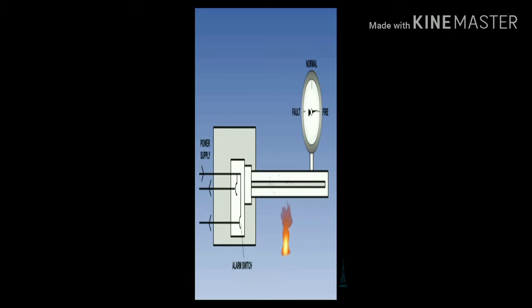The Kidde continuous loop system can supply nacelle temperature data to the airplane condition monitoring function of the aircraft information management system, AIMS. The rate of change of resistance identifies an electrical short or a fire. The resistance decreases more quickly with an electrical short than with a fire.